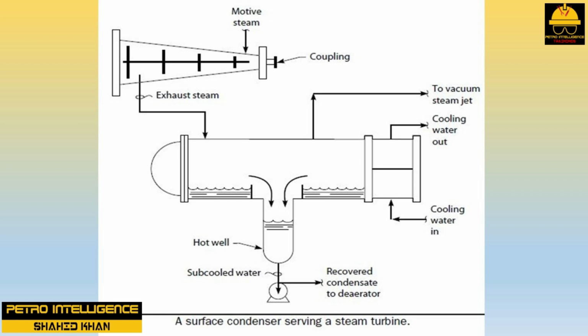The turbine is located above the surface condenser. The wet exhaust steam flows down into the top of the condenser shell. Note that the exhaust steam from an efficient turbine will contain several % of water. The shell side pressure drop of the surface condenser is quite low.